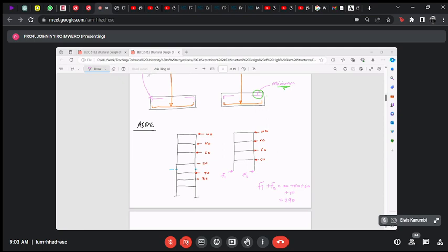then you don't have a shear wall. If you start with, for example, checking the shear and then the axial, it is possible that you find that they are okay, but then the bending isn't, because bending is the critical one. So we start with the bending on the shear wall, and then we check these other things.